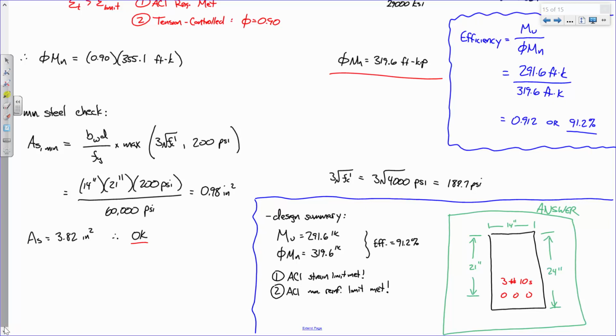Now the big question is whether you're using number 3 stirrups or number 4 stirrups, because number 3s are really, really small. But it's not a matter of the size of the bar, it's about how far you space them. If you've got a lot of shear, you'll just need more of it. You know what I mean? So that's what you do when you design for shear: you pick a stirrup and figure out how much you need. Number 3s or number 4s are options that you can use. You could go bigger, but you'd have some serious shear load on that beam. So to answer your question, yes, we will pretty much always have stirrups in our beams. It's because of the shear. That's a great question. Any others? This is good stuff.